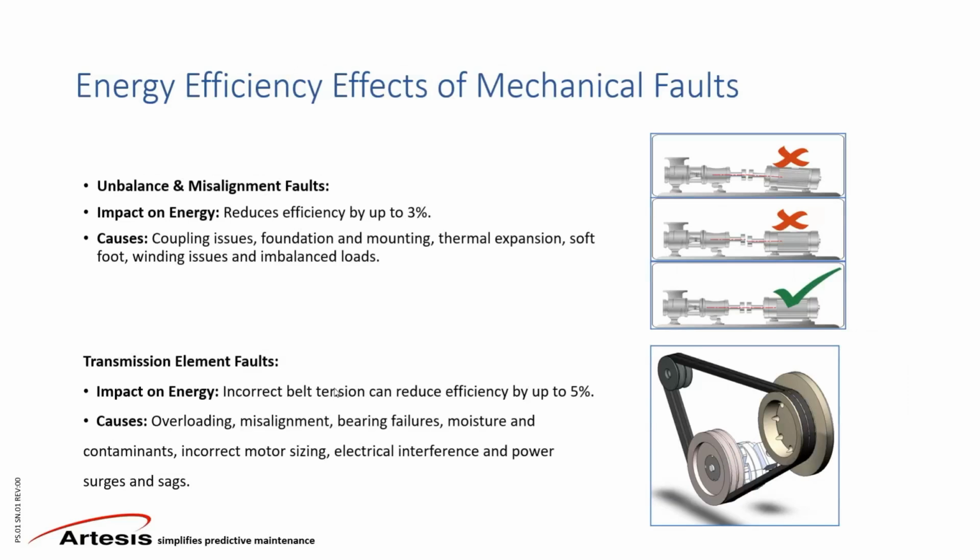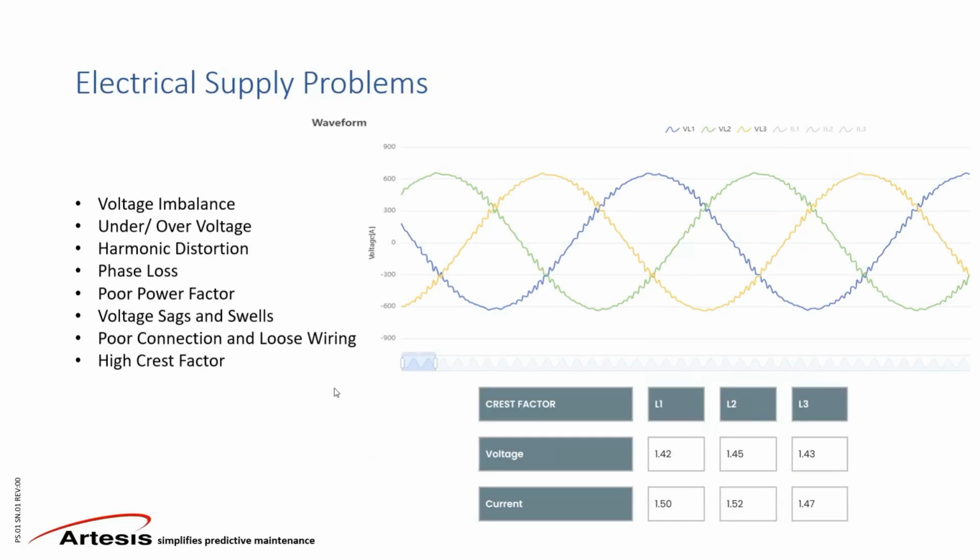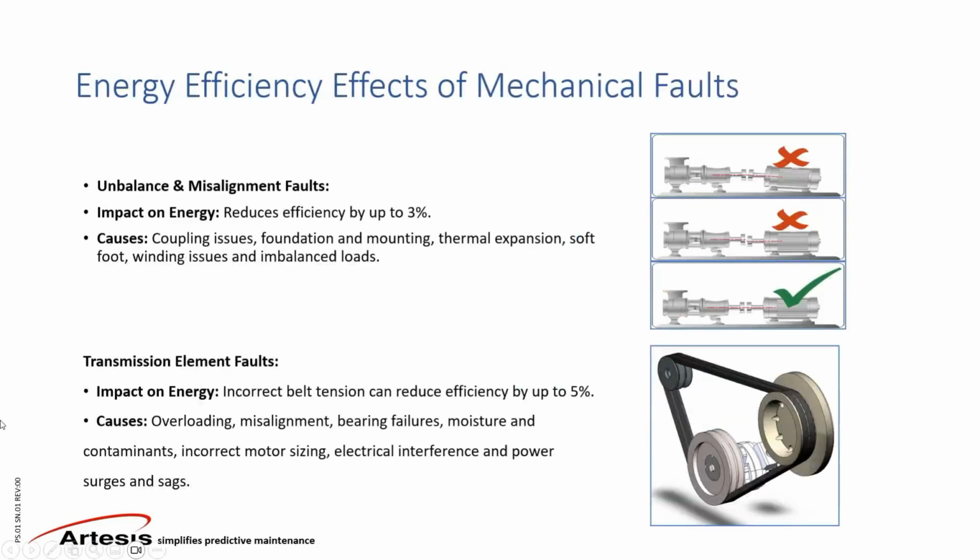belts, again, sheave misalignment. So these type of faults, again, will have the highest effect on the energy efficiency, not on the motor side, but if you think in simple terms, you have the motor inefficiency, so the electrical power converted to mechanical output, and you have the power at the shaft now, but that power from the shaft will be transferred to the fan through the belt.